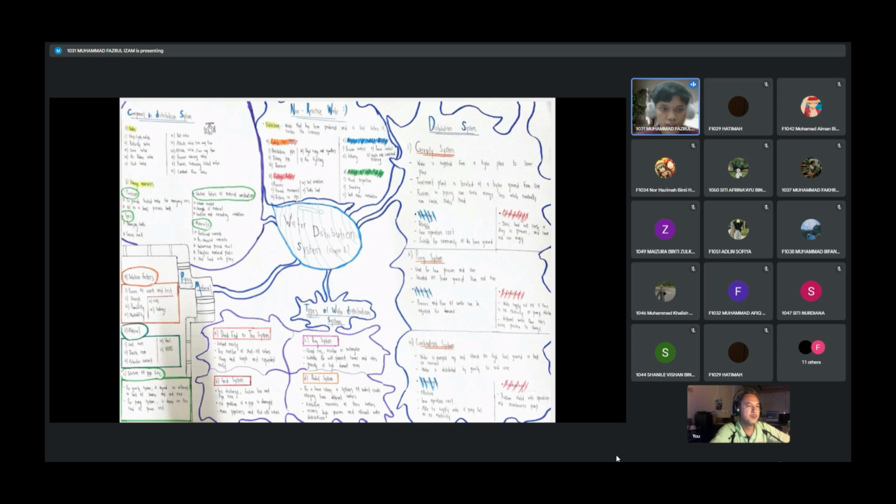First, we will learn about its factors of leaking, and then the measurement procedure for the leakage factor, where there are 2 types of measurement, direct and indirect. And then we will learn about the methods to control and detect the leakage. And lastly is the piping design with the Hazen-Williams formula.